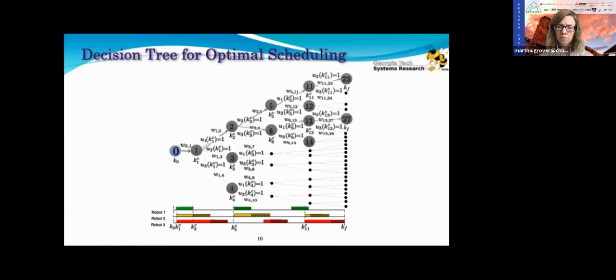So we can just keep doing this with the help of the timing model to predict when the contention can happen, and each contention corresponds to one node in this tree. And then we can use the MPC cost function to calculate the branch cost that characterizes the robot performance for each branch, in other words, in between each possible contention. This tree looks pretty complicated. However, we actually do not need to construct the entire tree in order to find the optimal schedule. In this case, the optimal schedule corresponds to the shortest path marked by these red arrows along this tree. So our job is to conceptually understand this tree, but then use a smart algorithm to search for the optimal path without constructing the entire tree.